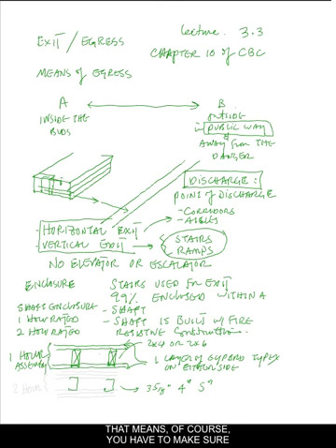That means, of course, you have to make sure that all the joints are covered, taped, and there is no area with holes or anything. You cannot make a hole into these walls because of the smoke that might get into them. So you need to keep them completely separated and isolated from the inside. The inside of them has to be completely isolated by these enclosures. If you add 2 layers of gypsum board 5/8 type X on either side, then you achieve the 2 hour assembly.